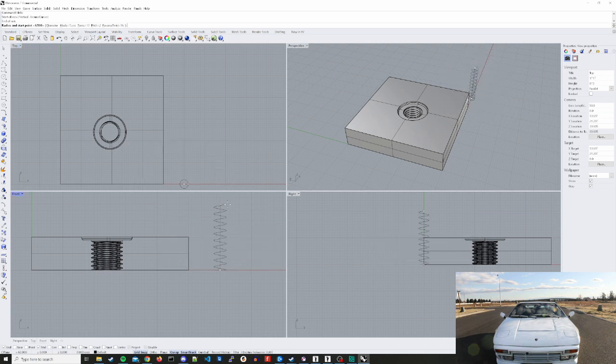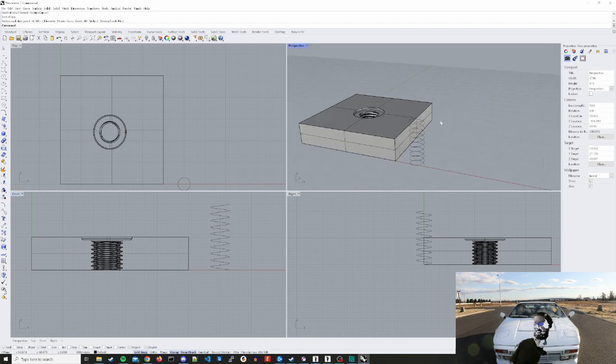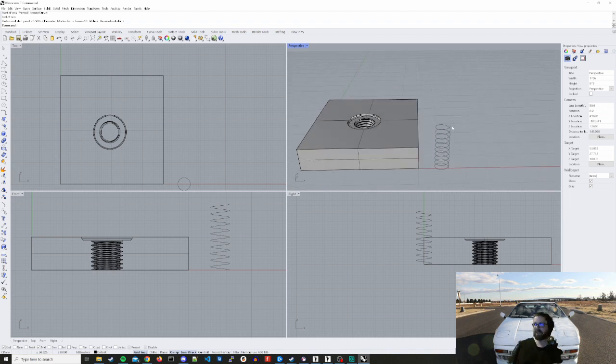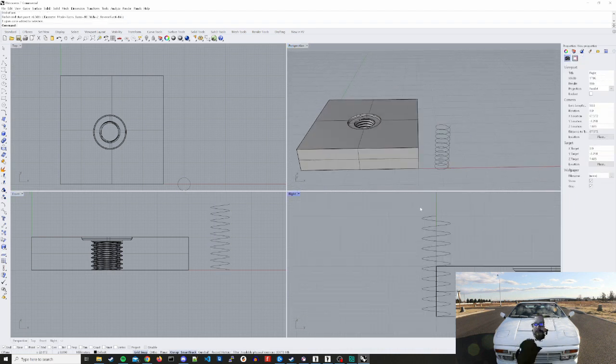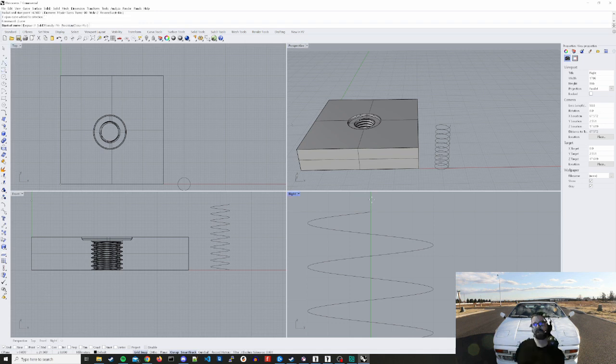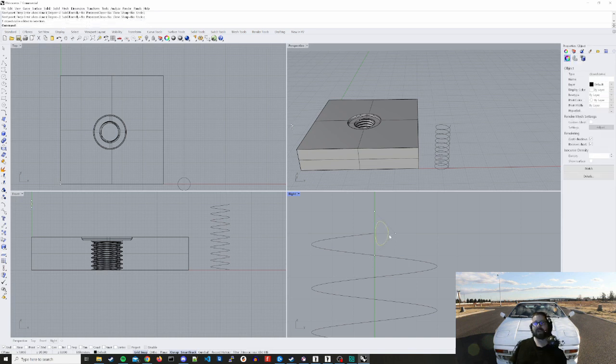And then you set the radius and the start point, and then figure out what the pitch is. There's a lot to doing this. On top of that, you would then draw a curved line based on your calculated size of the threads to make the solid, and then you would sweep the rail and close the surfaces, and you would extract it from a cylinder.